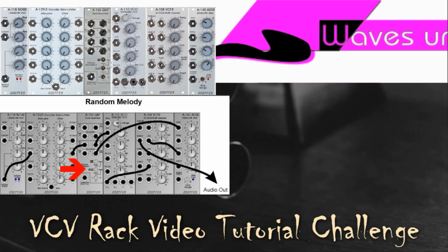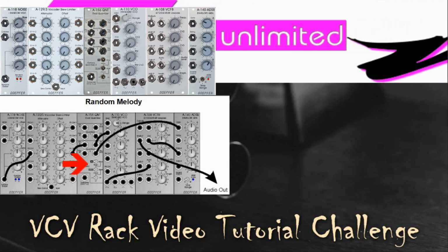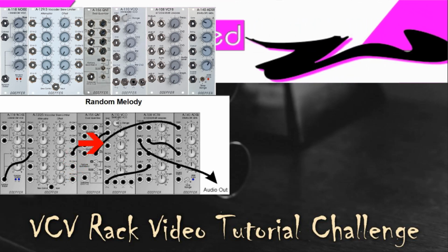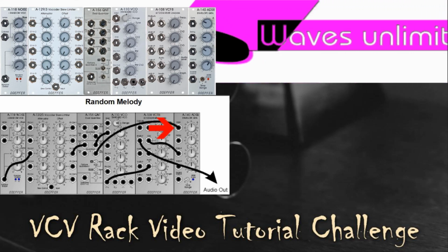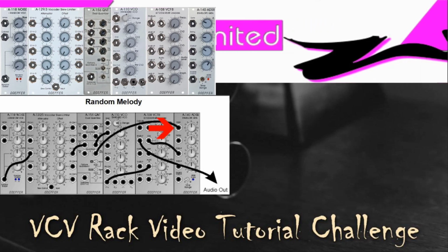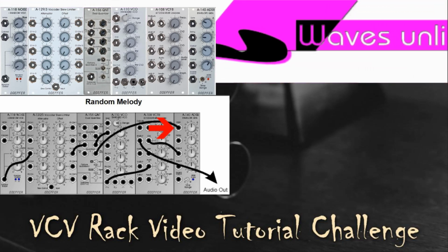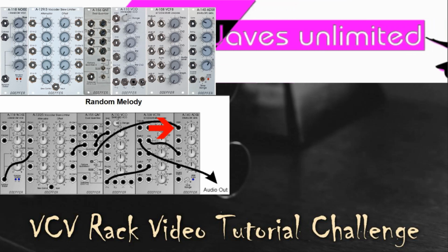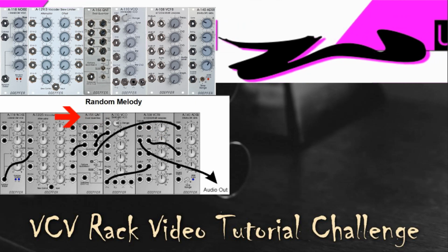The trigger output of the A-156 is used to trigger the A-140 envelope generator for the filter. It is possible to synchronize the patch, e.g. with a sequencer. For this, the trigger input of the A-156 has to be connected to the main clock source.